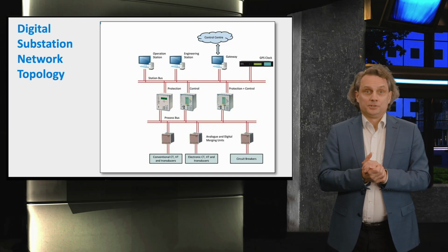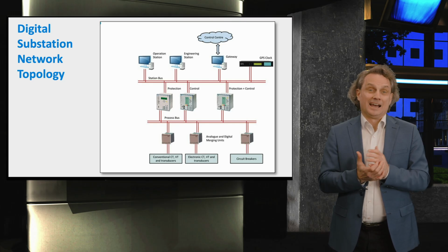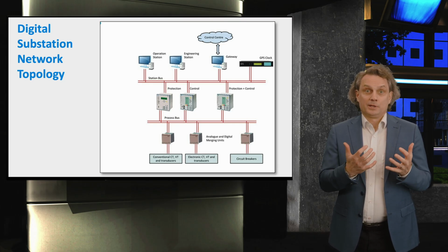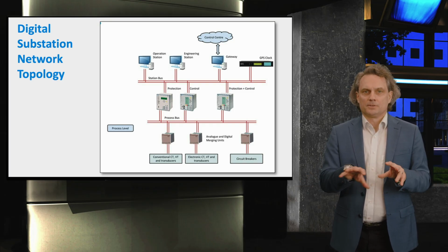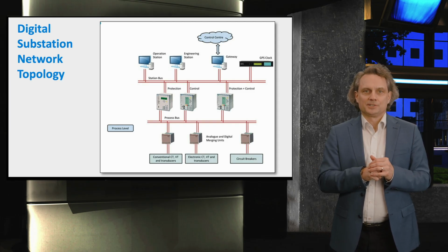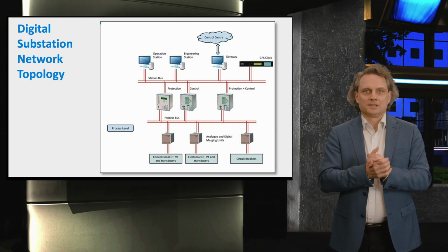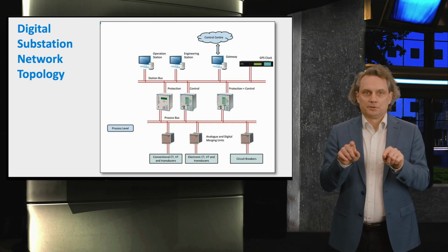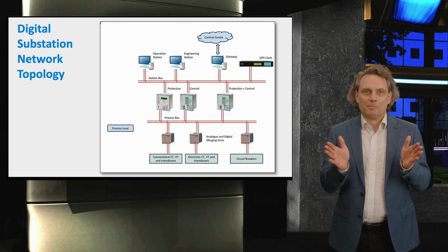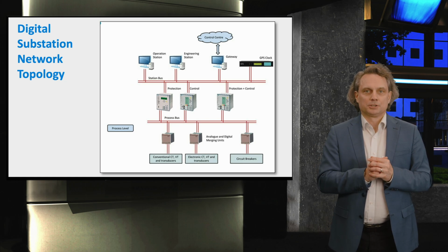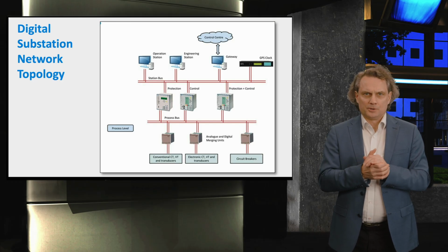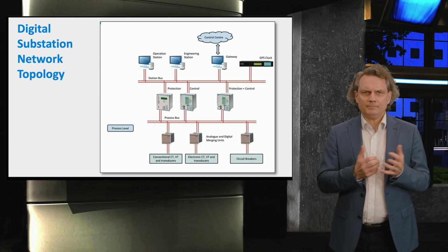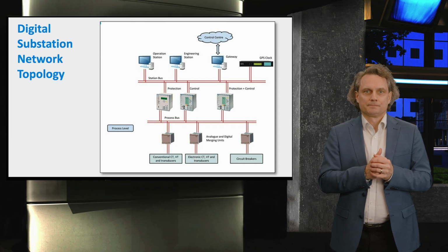The IT architecture of these new substations can be broken down to 3 levels. The primary equipment is connected to the process level, the base of our architecture. Here we have the measurement units with sensory devices, which can be analog or digital. We can also merge data at this level. For instance, when measuring 3-phase voltages, we typically combine the measurements into one data package. So at the process level, we have sensors for current and voltage. We consolidate the data and send it via optical fibers to process it.